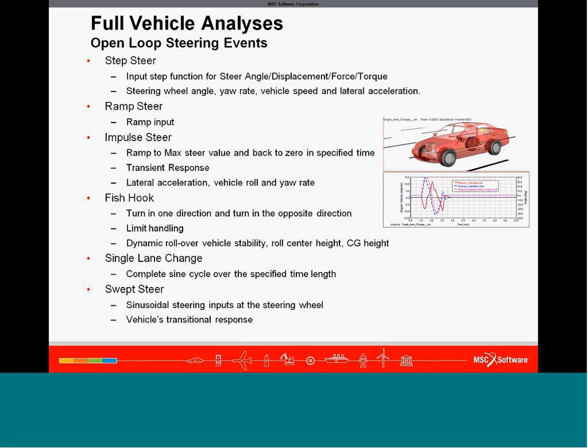And you can look at different vehicle characteristics. When you do a swept steer, what is the transitional response of the vehicle? When you do ramp steer, how does the vehicle react? What is the yaw rate? What are the tire forces, etc., as you keep on increasing the steering ratio.